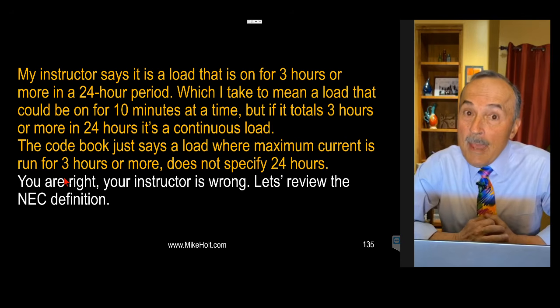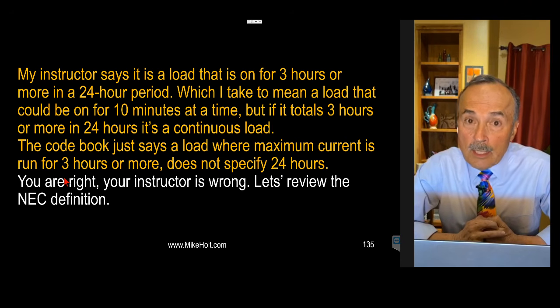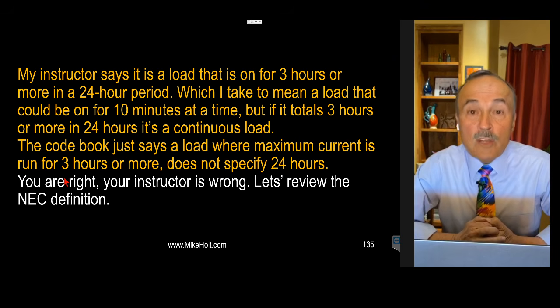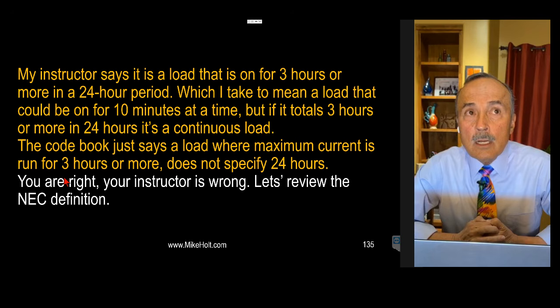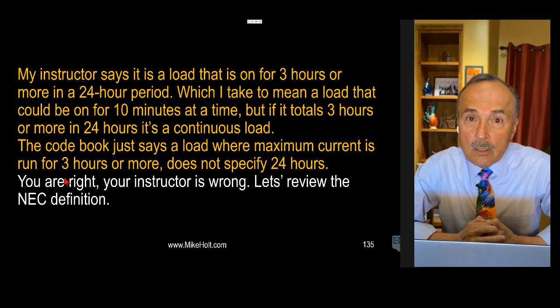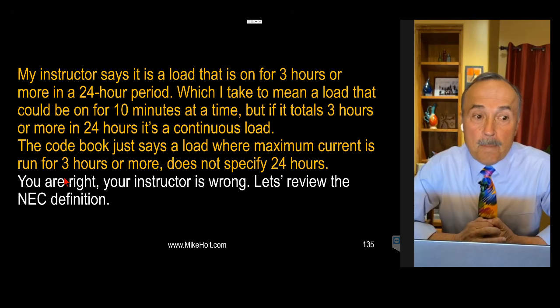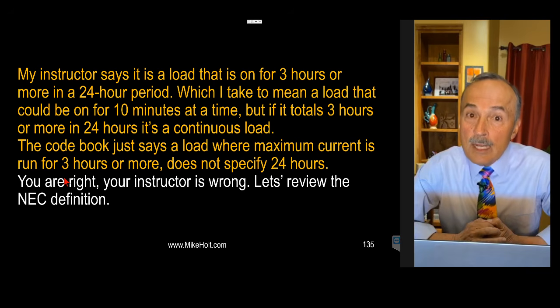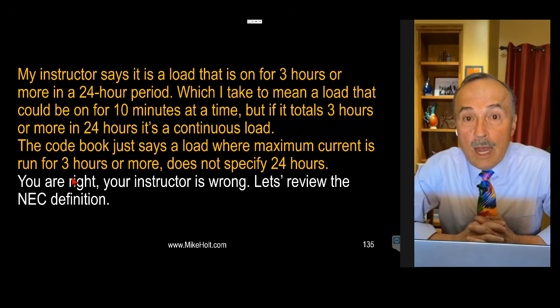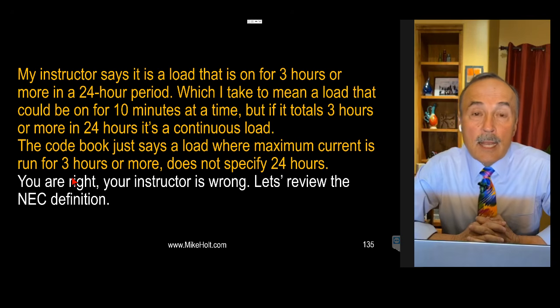That's not the way. Now, do they make a breaker rated for 100% continuous operation? Yes. So if you have a 100 amp breaker and you have 100 amps continuous on a 100% rated breaker, you could size the wire to 100 amps, you could size the breaker to 100 amps, and you can carry 100 amps current on it. But if you don't get a 100% rated breaker, then you have to size the load to the wire and the load to the breaker to no more than 80% of its rating.